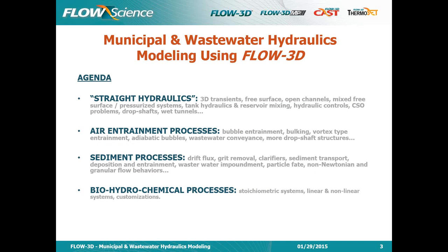Municipal flows are very interesting because there's really quite a lot going on. It's usually complex. It's also eminently practical, and I would say highly consequential, since generally we are dealing with the built urban environment and or sensitive environmental considerations. So there's really a whole spectrum there of modeling interests. Some of the topics that go hand in hand with what I think of as the straight hydraulics part of the puzzle are sediment and grit transport, also sediment deposition and entrainment or re-entrainment, and air entrainment as well. And then also chemical or biochemical reactions and the way these couple with the hydraulics of a fluid.